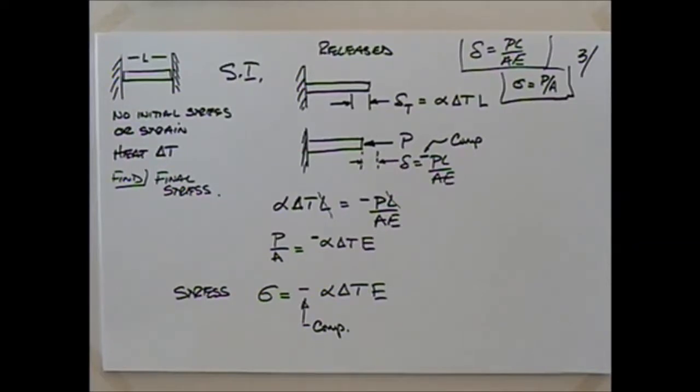But their task was to find some mass properties of these bugs in terms of center of mass and things like that, and trying to figure out how to make walking machines from these bugs. And bugs are fairly uncooperative with that, so they would cool the bugs down so the bugs would stay nice and still. And then they had a spring system to try and make some of these measurements. And the question came up during their final presentation, did they calibrate their spring at room temperature or at the reduced temperatures when they were trying to measure the cold bugs? And they didn't calibrate it at the reduced temperature.